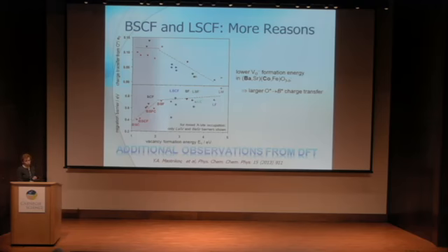Just a little bit more reasons to show how BSCF and LSCF are different. We looked at the diffusion of vacancies in both materials and discovered there is charge transfer. And this charge transfer in the transition state is different. In BSCF, there is a large charge transfer, which actually affects kinetics and diffusion barrier. In LSCF, it's not.